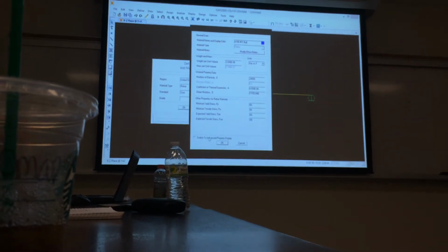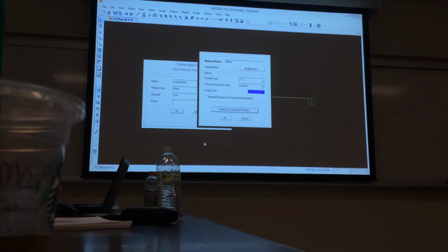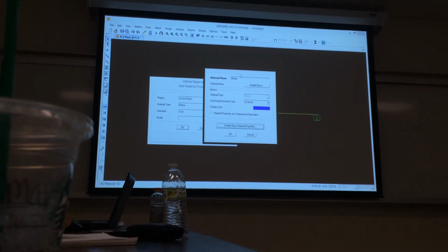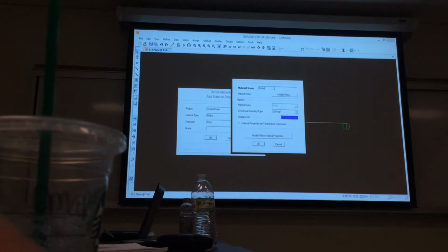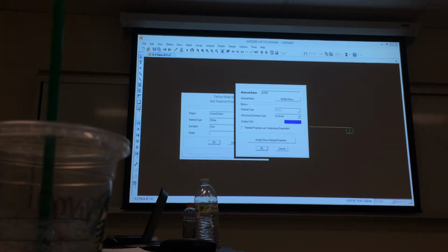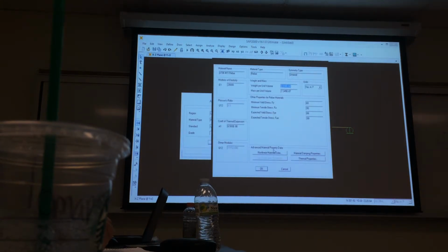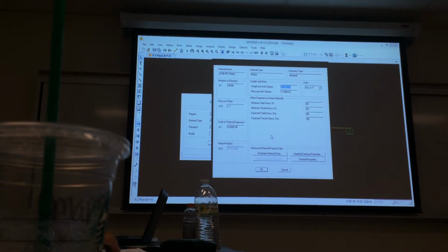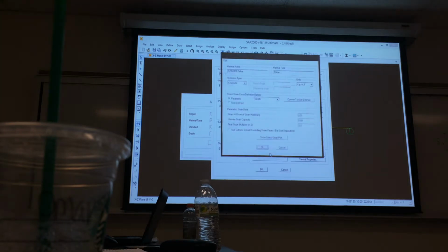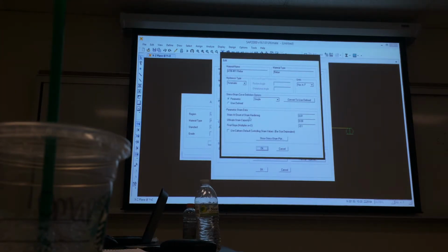In this case, I want to go to Advanced Property Display. You want to go to Show Material Properties and go to Show Nonlinear Material Data. SAP oftentimes will let you use its inbuilt equations.